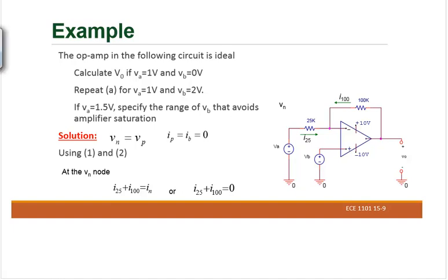Let's see here. If we have this circuit, I'll assume first that VB equals 0. We have VA right there, V out right here, feedback 100K, and next to our input voltage, the input resistance value. First thing, number 1, do we know VP? Yes, VP equals 0. And we know that VN will be equal to VP. That will be equal to 0.